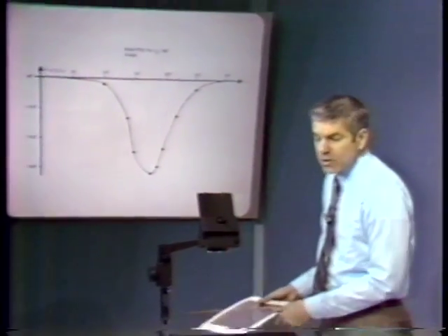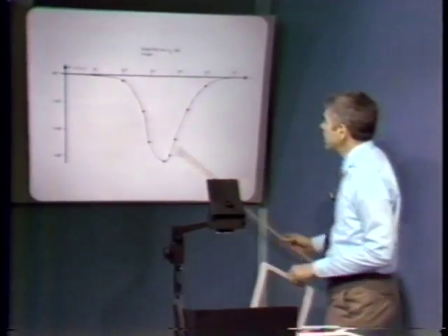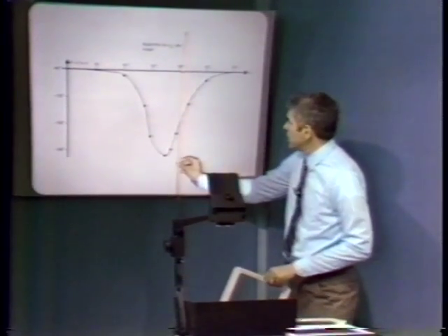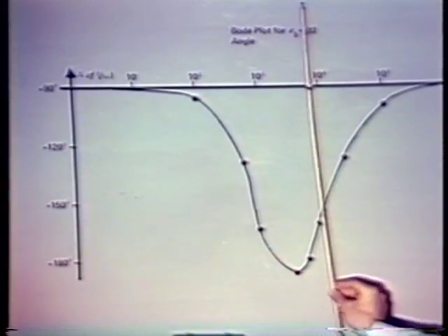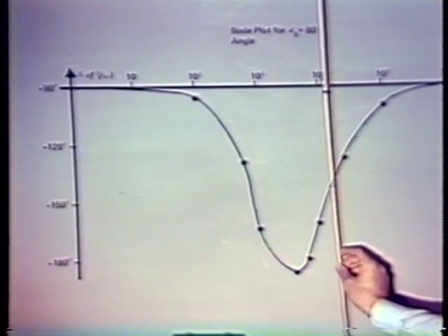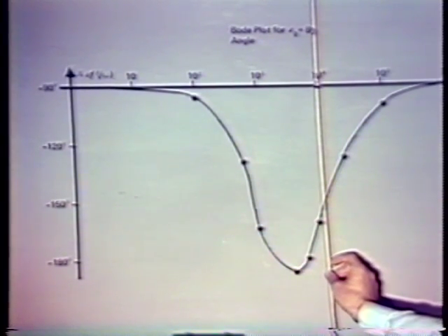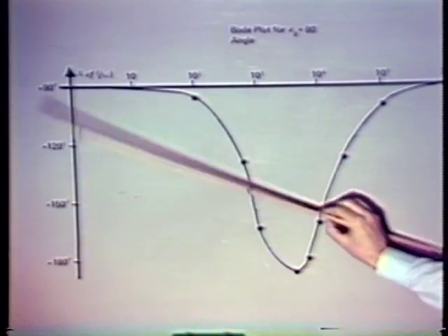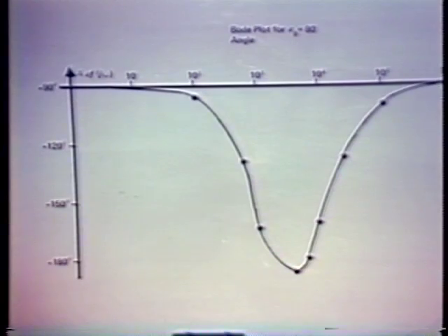Here's the angle portion of the Bode plot. If we look at 10 to the 4th radians per second, we have a positive value of phase margin. So again, with A0 equals 80, we'd be crossing over, as I had indicated in the original Bode plot on the board. We have a positive phase margin.